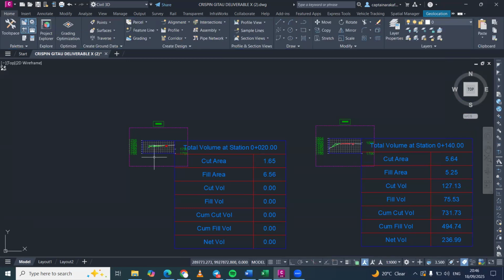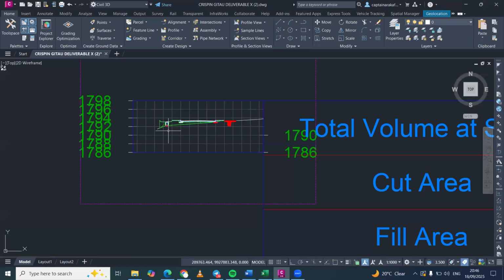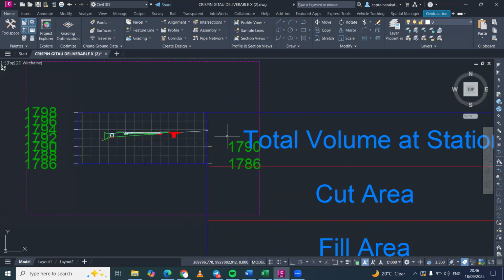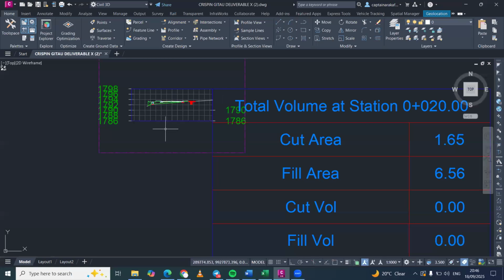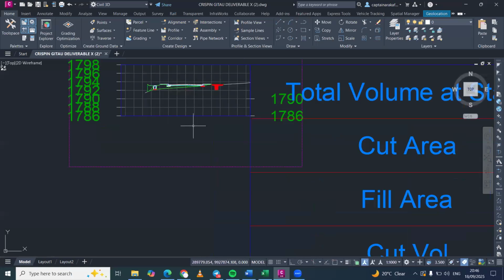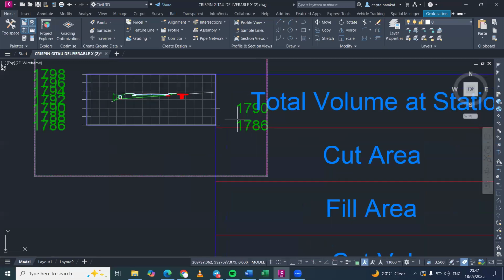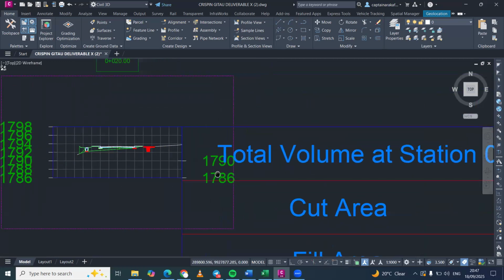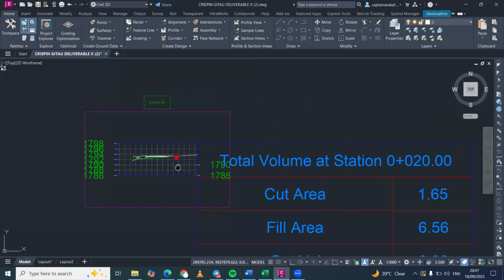Then we can get back to our section view, right? The text, the annotations are quite large. We can reduce that style or that size. We also need to reduce the size of the table, okay? Maybe we will reduce it 5 times smaller, we will see. And then we also need to display the bottom axis labels, right? We need to display them. Maybe we need to also switch off the right side annotations, right? The section is a bit small, so no need to have both ends labeled, right?